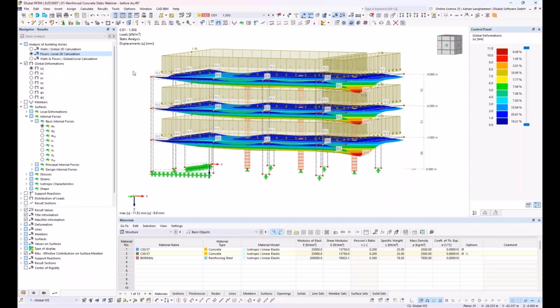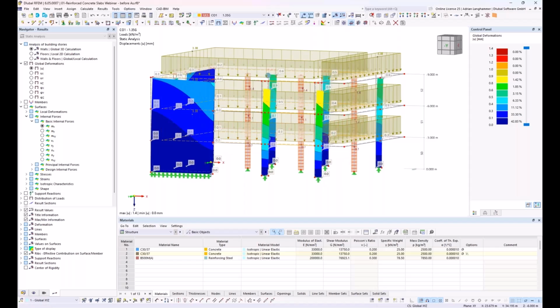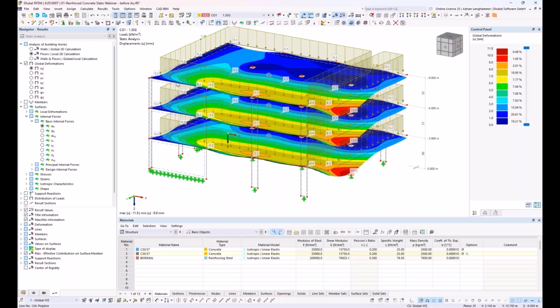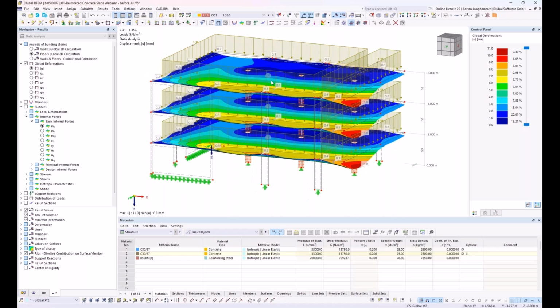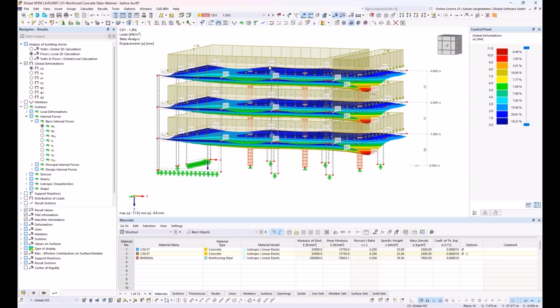Yeah, I also will show another point. The program, as I mentioned, calculates the walls here, connected via a rigid diaphragm, and the floors, let's say, as separated 2D positions, and it also calculates some load transfer based on a submodel which is calculated in the background.